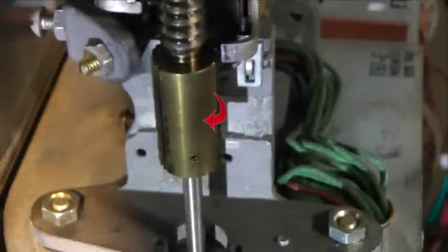Just below the vertical ratchet is the rotary ratchet. It is also attached to the shaft and moves up and down and rotates with the shaft. It provides the teeth required for rotary stepping. Each tooth corresponds to one horizontal terminal position on any level of the bank assembly. The teeth are engaged by a rotary pawl that rotates the ratchet clockwise by one step per engagement. Each step rotates the shaft an amount equal to the distance between two bank terminals.